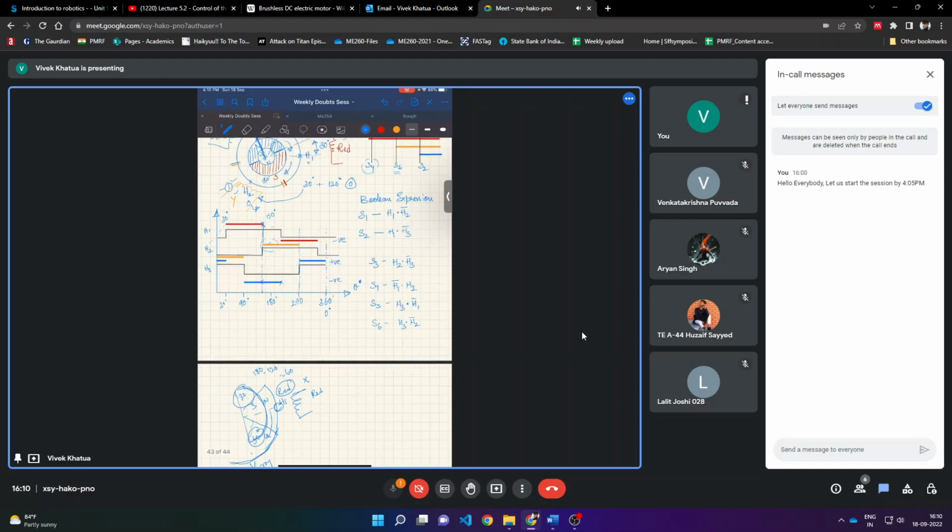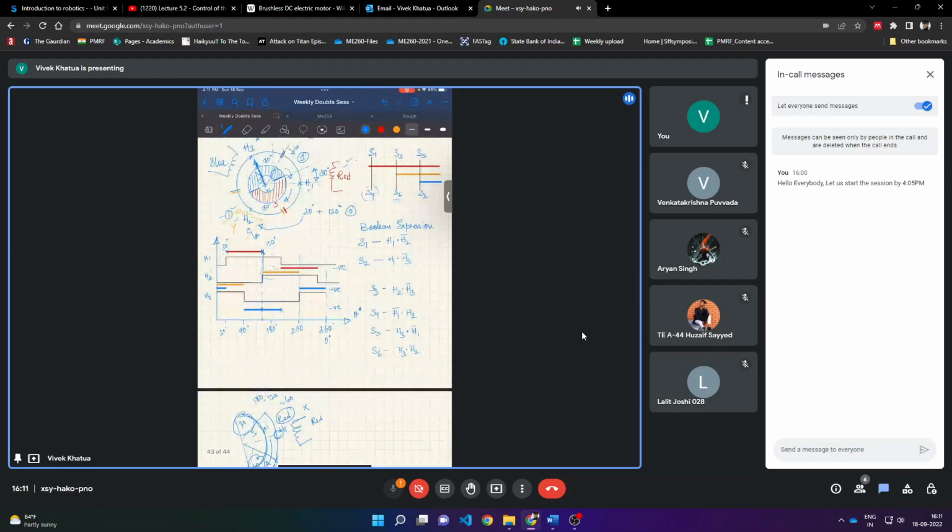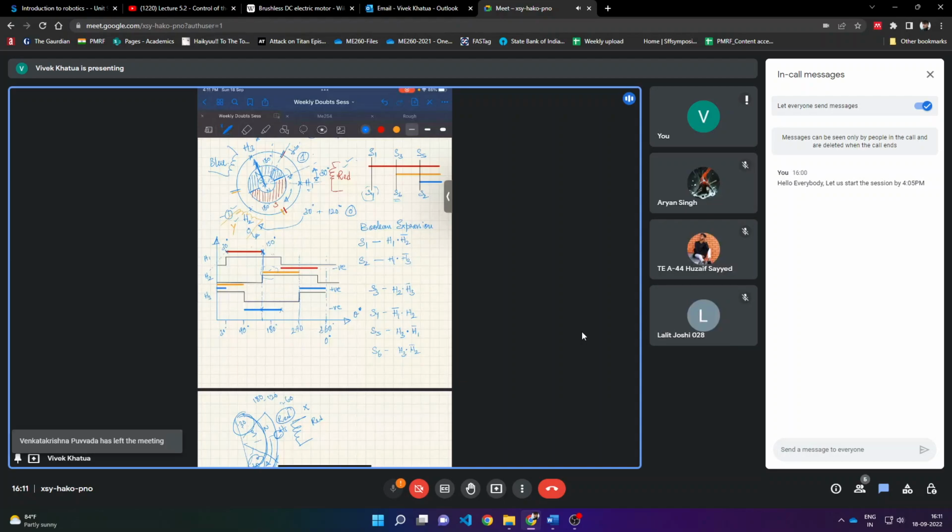So how would I get this 30 to 150 region? I need the information of where my rotor is and where it is going to go. Like it is in H1, and it wants to go to H2, near H2. So I would be using H1 bar H2, right?